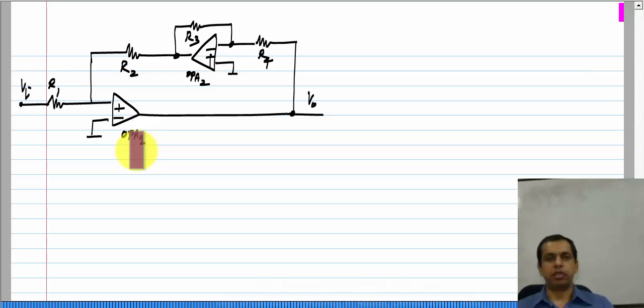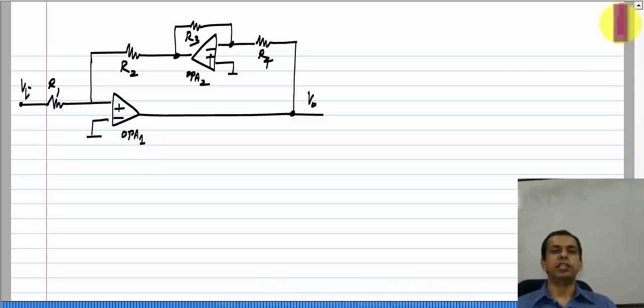So, one by one you remove the op amp and you replace the op amp's output with a voltage source and see the polarity of the returned voltage to the inputs of that op amp. I mean, doing that calculation, you have to do something with the rest of the op amps in the circuit. The easiest would be to assume that all other op amps are in negative feedback. So, their inputs are virtually shorted.